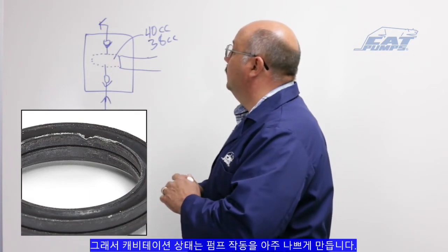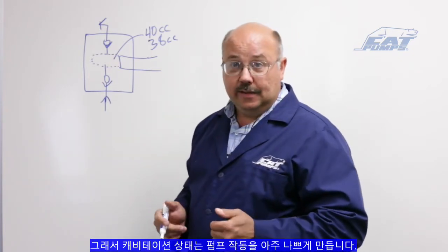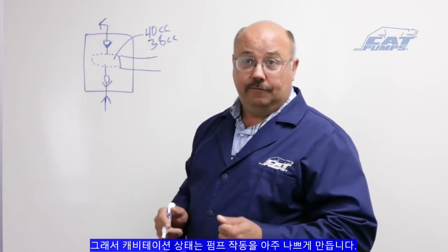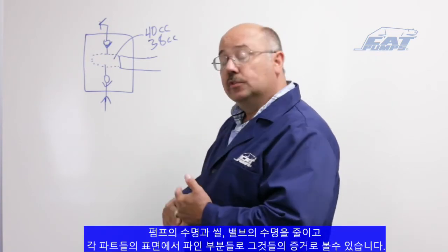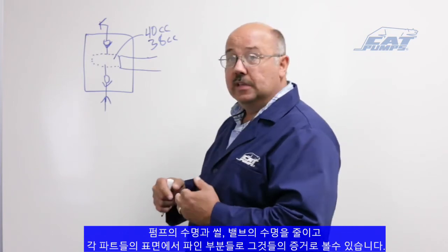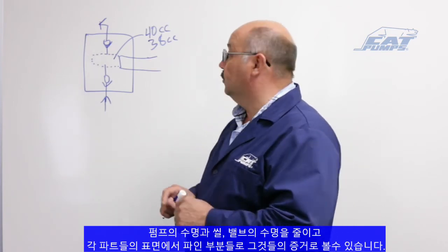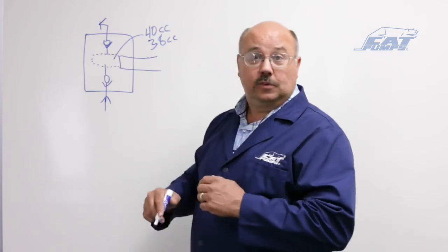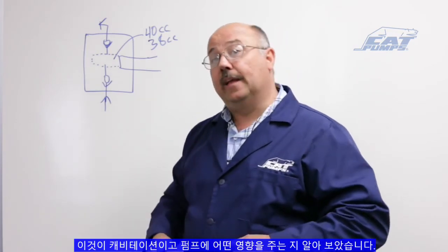So letting your pump run in a cavitation state is very bad for it. It will reduce the life of the pump, the seals, and the valves, and you'll be able to see it by evidence of the pitting on the surfaces of the parts. So that's what cavitation is, and that's what it does to your pump.